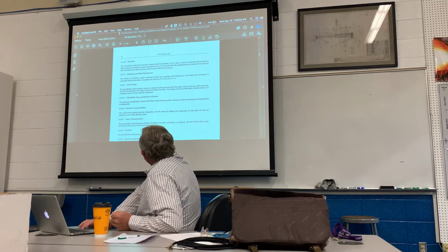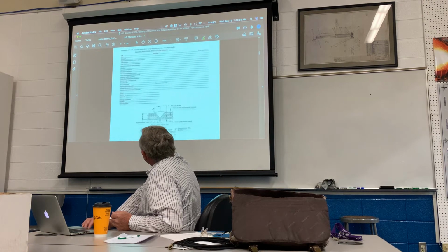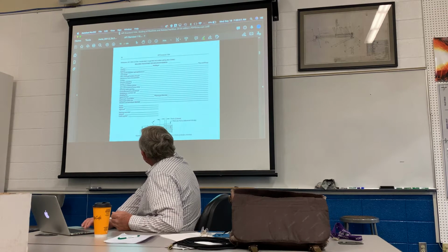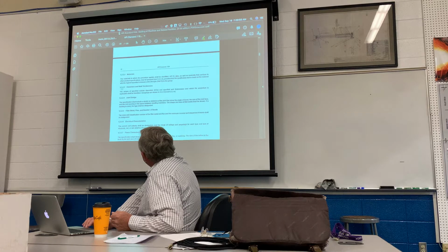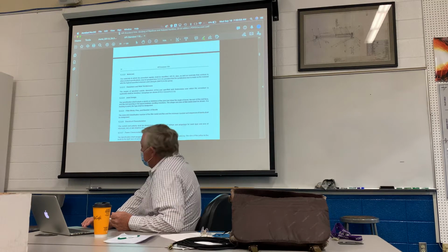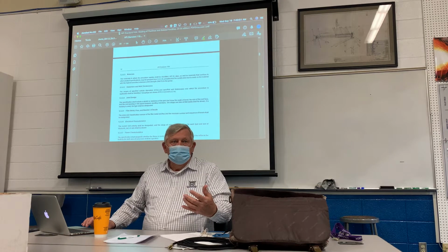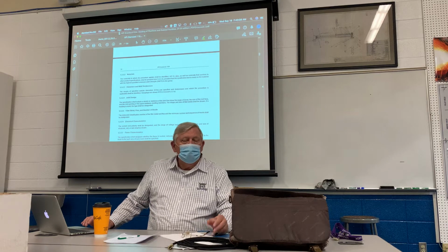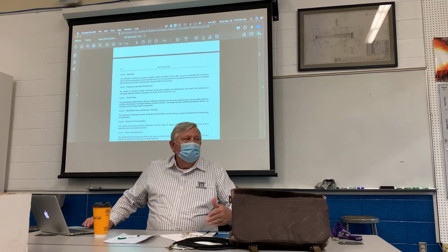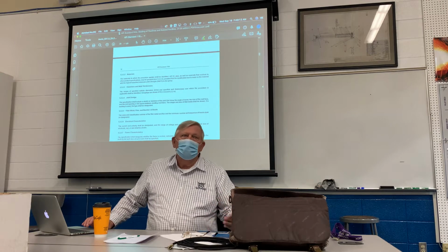Well, let's look at diameters and wall thicknesses. So you have this item on the WPS, pipe diameter outside and wall thickness. It's listed right there on the WPS. So what do we put there? You go down to this right here, 5.3.2.3. So everything's under 5.3, and they'll list a couple of other charts or other details that you might have to refer to. I don't think anybody requires you to memorize the grouping chart for welding rod.